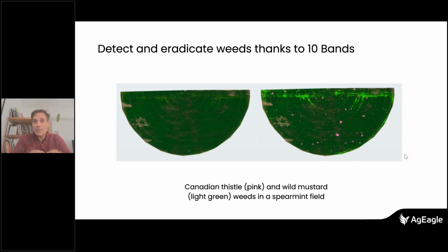when we need to make a map, we do it with photogrammetry, we need overlap between the pictures, and these points between two different pictures are matched together, right? And then we can make this mosaic. But if you fly over water, there are no points that match because the waves are moving all the time. The angle of the sun is different between every picture. So it's very, very hard to make a map over a water body. What you can do is make maps of coastal areas or just look at the individual images.